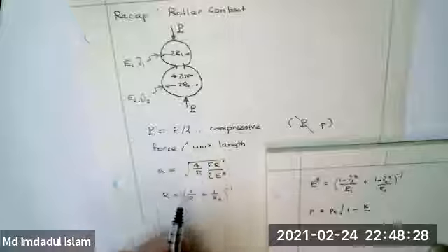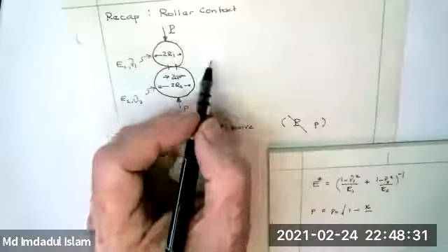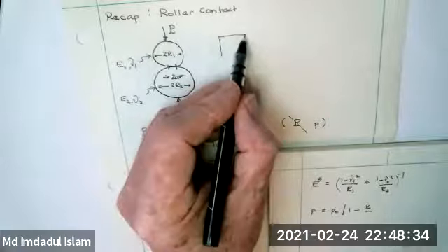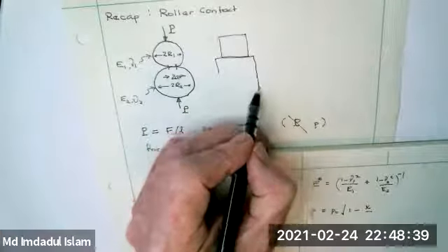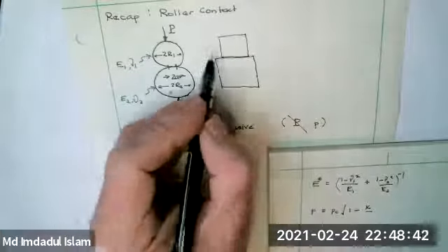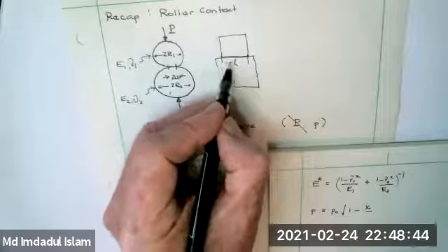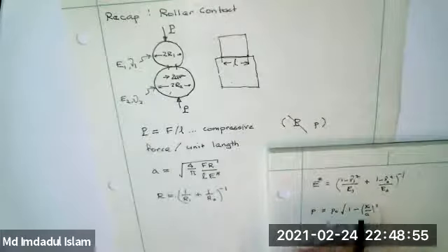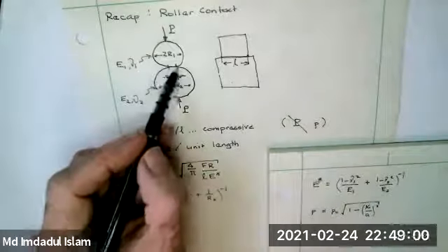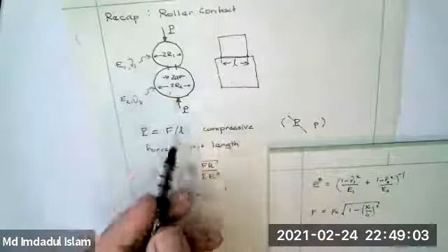just to be clear, that L is the length out of plane. All right, thank you. Let me clarify that. So let's suppose this was bigger than this, then L is the net length that's in contact. So per unit out of plane length. So you get this distribution that goes to 0 at x equals plus a and minus a. X is the dimension across the contact region.